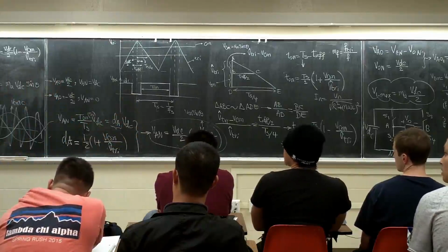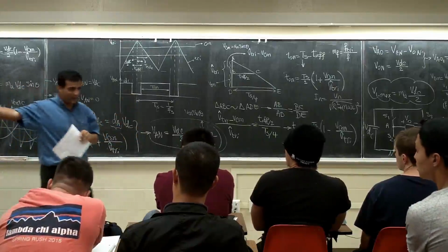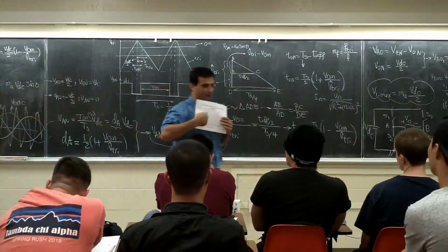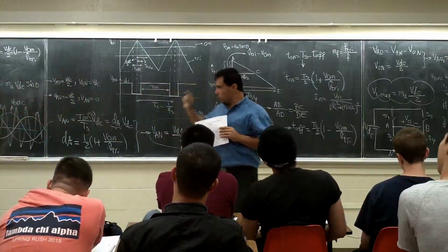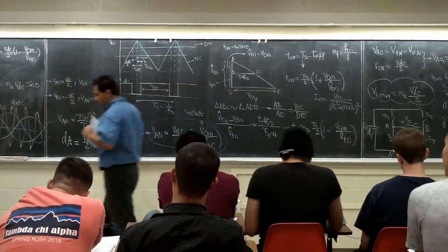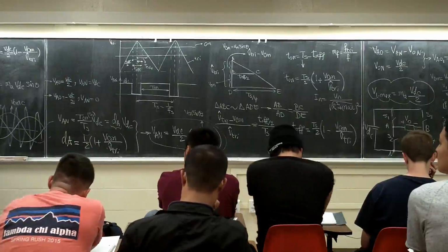That's a good thing. Now we are pushing harmonics away. We are not getting rid of all of them. Yes, they are going to be big, you can see the table. But the good thing is the number of harmonics is very high. In general, for bipolar switching, you are going to see this kind of harmonics in the output.